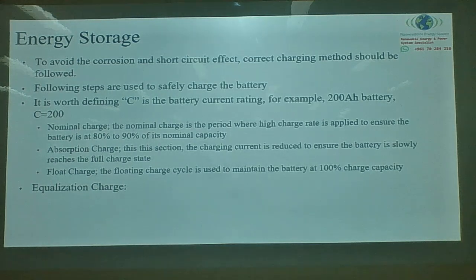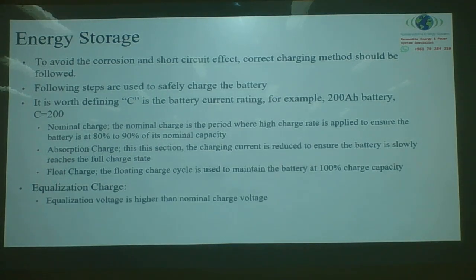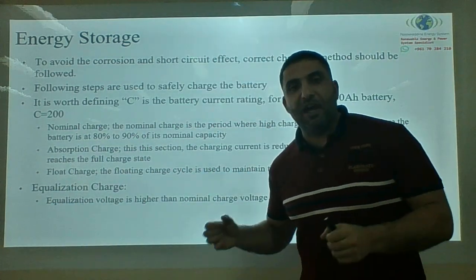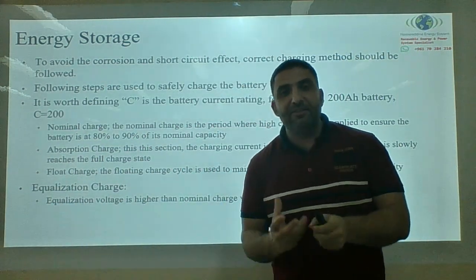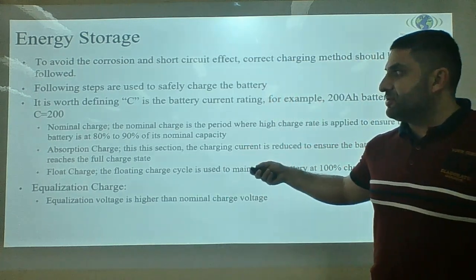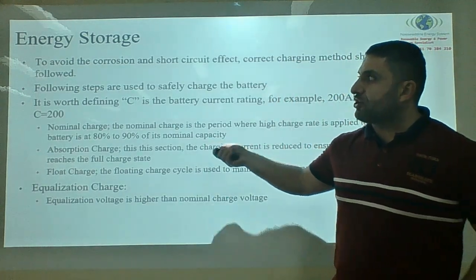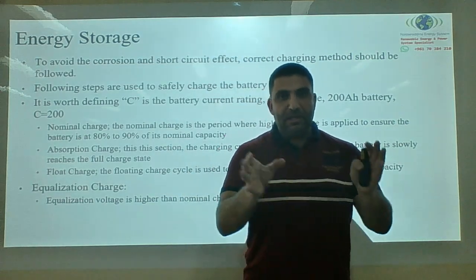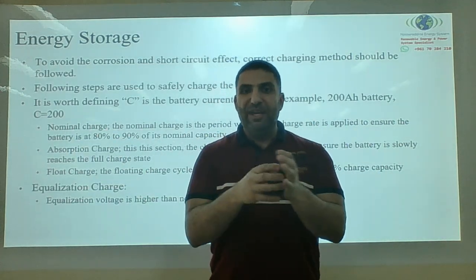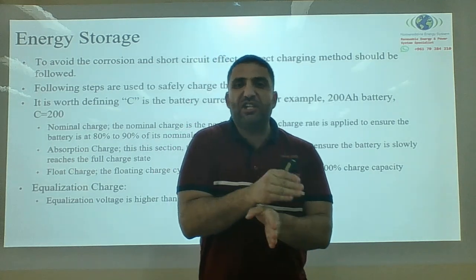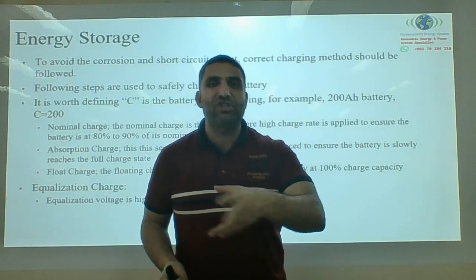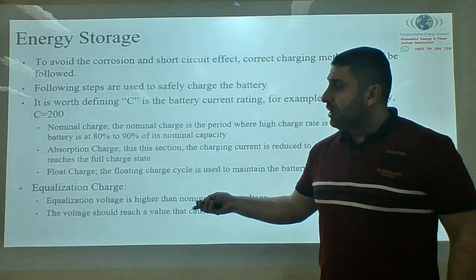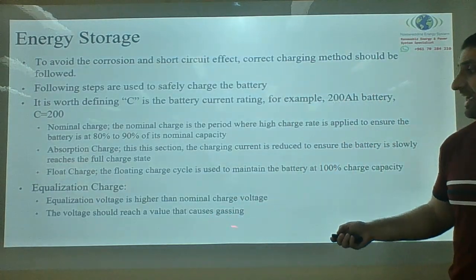What's the equalization charge? Sometimes you need to revive the battery, to shake the internal reaction. Because of bad charging, not all the cells are discharged at the same rate when the charge goes through. Not all the cells are charged at the same rate. So what I do is I apply a voltage to cause gassing.